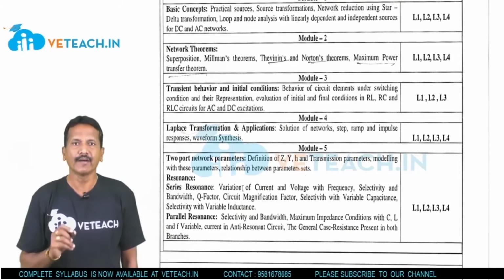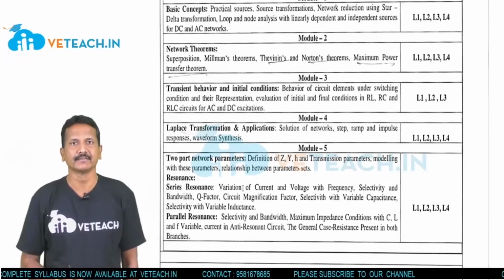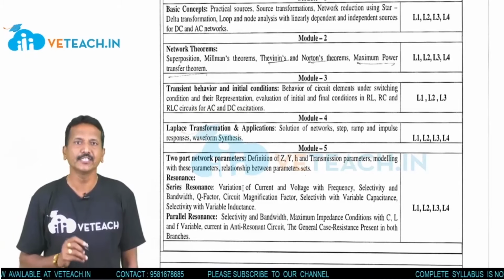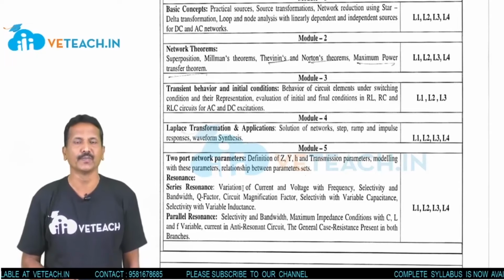Right? So our bulb is there. Bulb is a resistive load. Iron box is a resistive load. Our tubelight is there. Tubelight has a choke, that is an inductive load. A motor is there. A mixie is there. Inductive load.